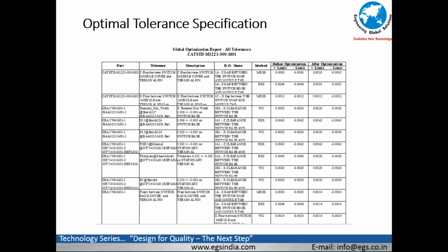It could be a serialized production process, in which case Monte Carlo simulation can be used to simulate the number of components coming out of the assembly line. Or you can use the worst case approach if fewer components are coming into assembly and fewer products are coming into the marketplace. Or you can use the square root of sum of squares method, or the process-centric approach, or the modified process where the deviated processes can be studied. In the event of a deviation in a process, how much would the yield vary? All these things can be done from a digital model even without one prototype being built.